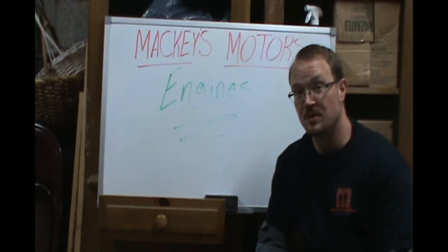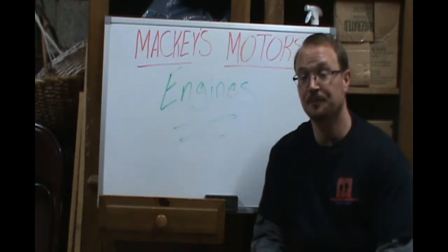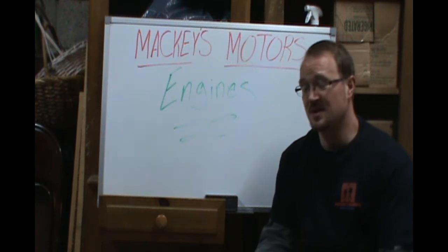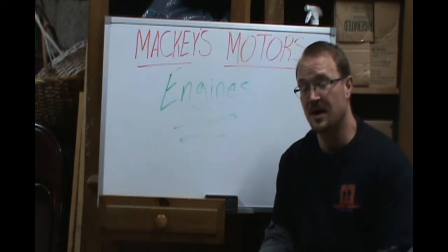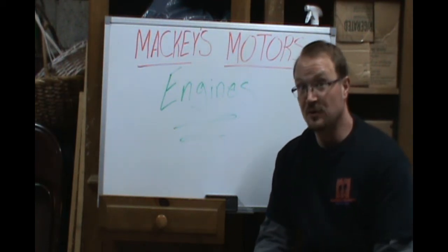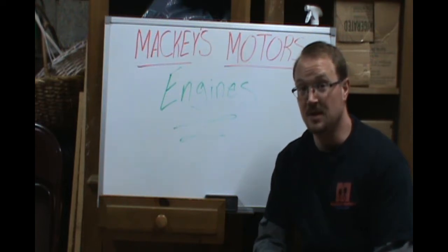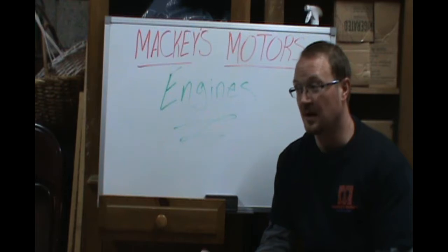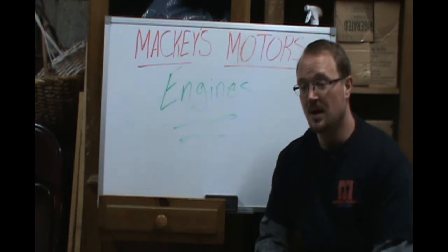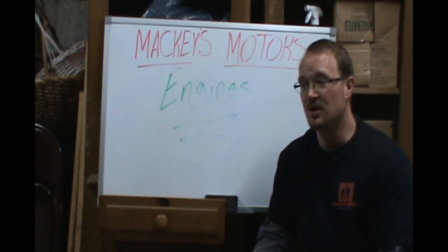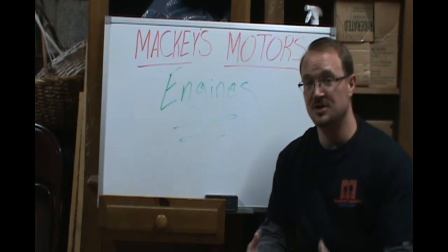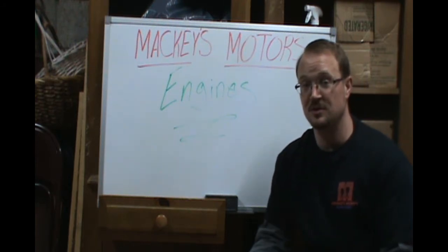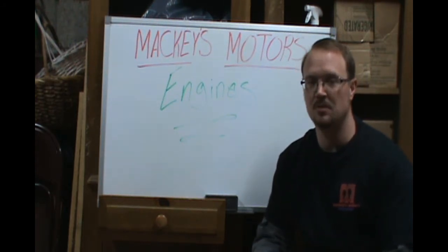You have to check your owner's manuals or with the manufacturer, and changing other things like PCV valves if they have a crankcase ventilation. Air filters are very, very common. We need to keep on top of those and keep those clean from all our road debris and from any contaminants in the air. And anything else, I mean, a tune-up can be anything from just changing spark plugs and filters to changing hoses and belts.